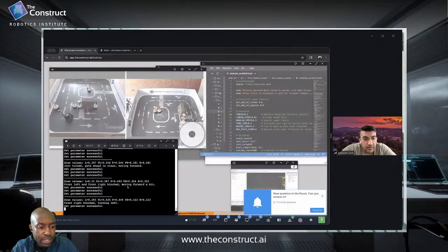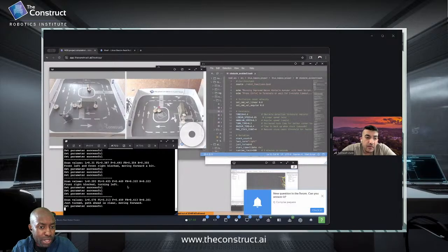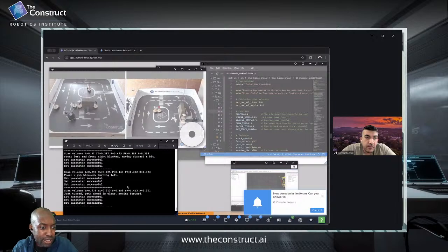That's why I was worried when you said you used 0.1, because if it's 0.1 and your robot has got a radius of, let's just say, 0.5 or 0.35, right? Then 0.1 means it won't be able to rotate either left or right, because when it tries to, the other side touches the wall.